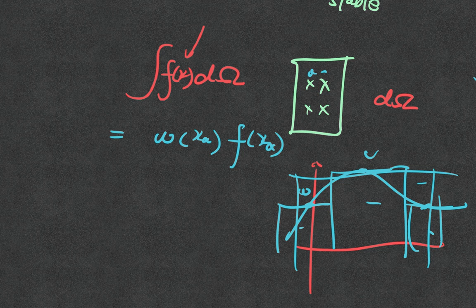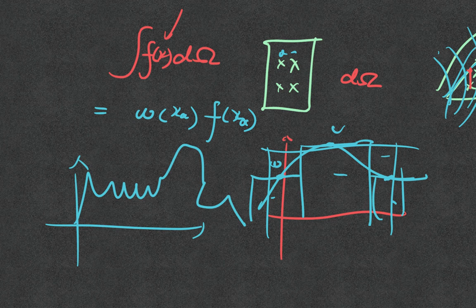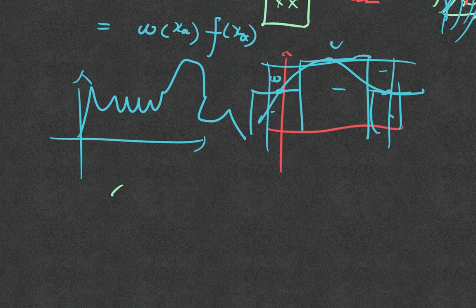That's it. Now, why do I say that? When you integrate the solutions, you have multiple choices. You can think about this. If my function looks like this, how many Gaussian points do I need? I need a lot of points, basically, and I need a very refined way. In fact, in extended finite element, even in 1D, I want to integrate this, or maybe not exactly like this, some kind of jump.